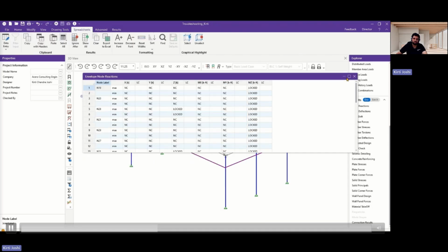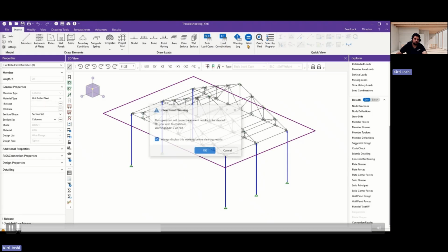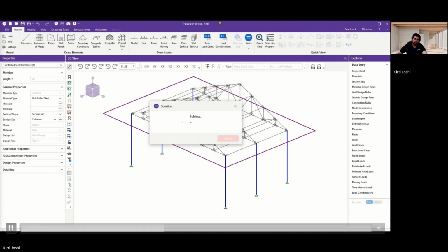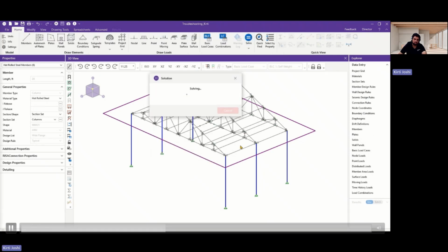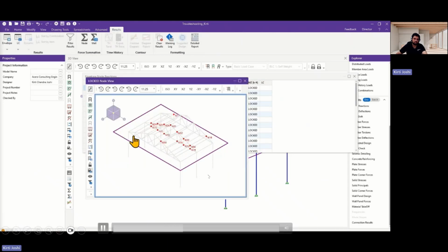What I mostly used to do is this, and you can again select your truss members by going to select by property. First, let me solve this issue, because at the top we are also getting some releases. Now, at the top of my column member, we are not getting any kind of instability because we have removed the releases.